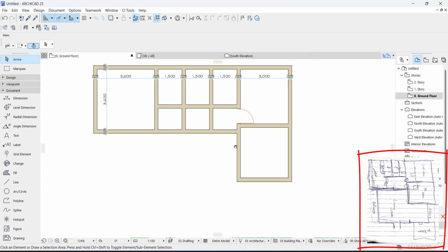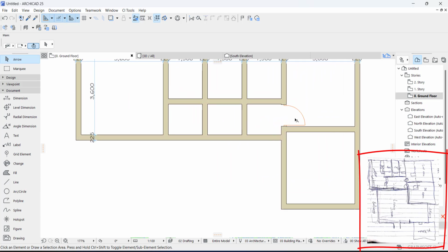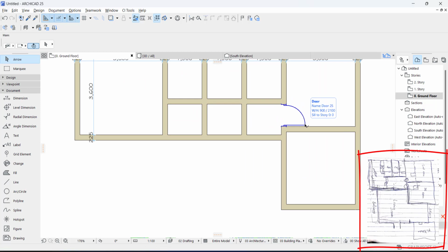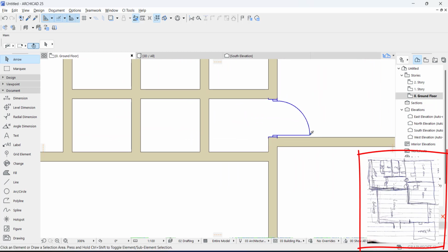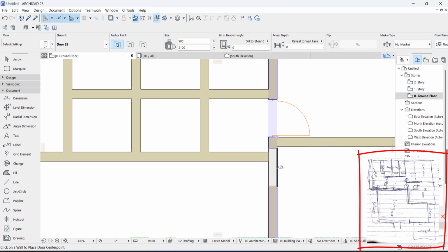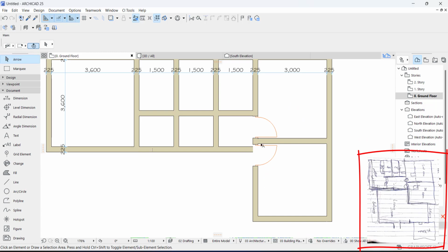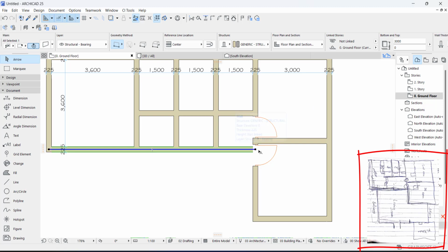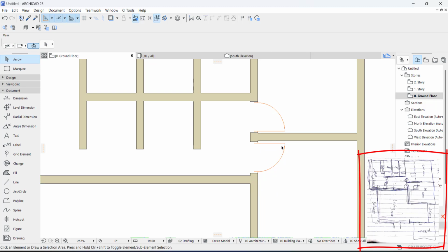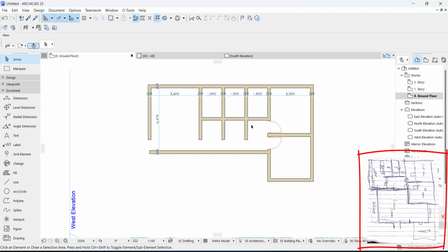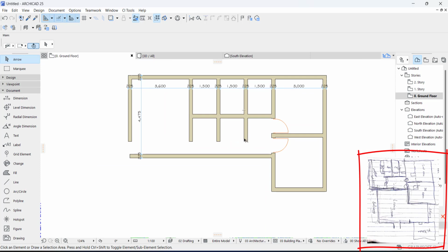Okay. Now you said there is a door here also. So I'm going to use alternate and pick this door. Press the alternate down and pick that door. So it's active and you can place your door here. Now you said your lobby has two doors, just like so from your lobby. It simply means this wall cannot start here. It has to start somewhere around here. So I just moved it with Control D. By now you should know what I'm trying to do when I move a wall.